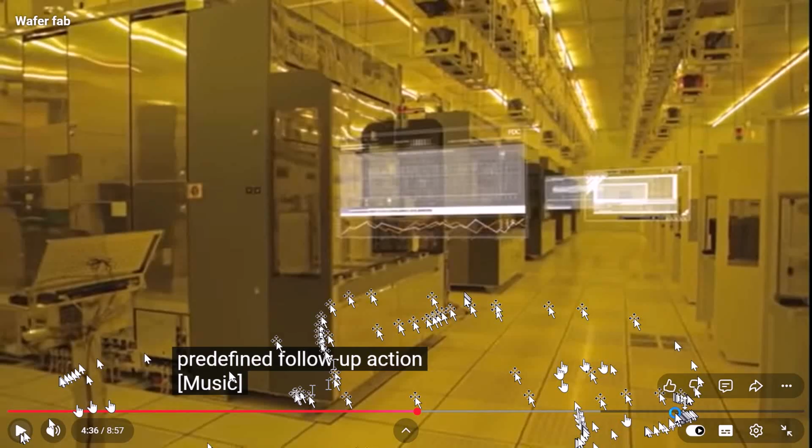Not only after the semiconductor processing, but maybe after the transistor, we do it again. And after metal 1, after metal 2, we need to do the WAT a lot in order to make sure which metal line and which process flow is going wrong. So we need to know what's happening for each processing step. That's the reason we do the WAT a lot.